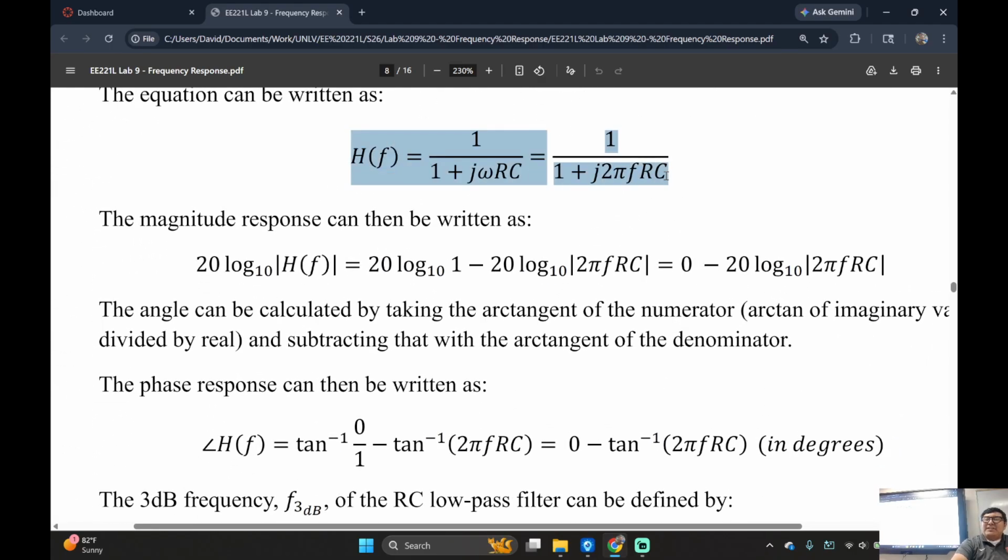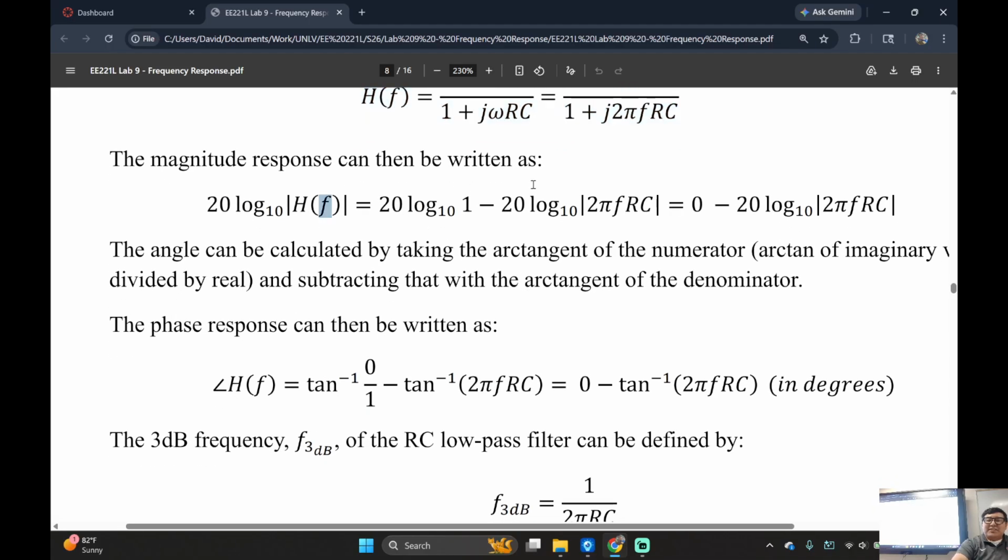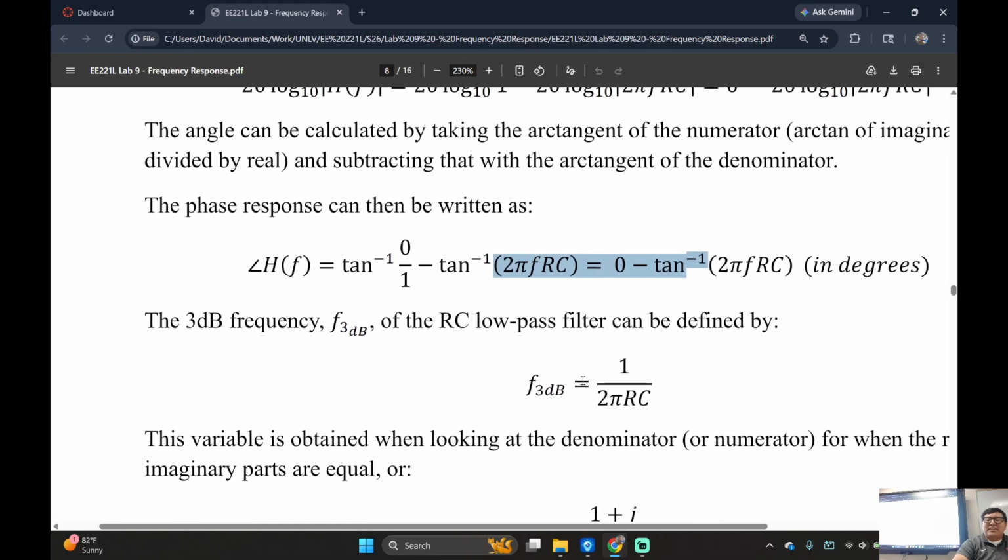Do you guys understand this right here? Transfer function in terms of frequency, linear frequency, correct? Not too bad. This is how you do your magnitudes, right? Your phase, and then this is how you get your pole, right? Your 3 dB frequency. Everyone can use this little calculation and get their bandwidths.